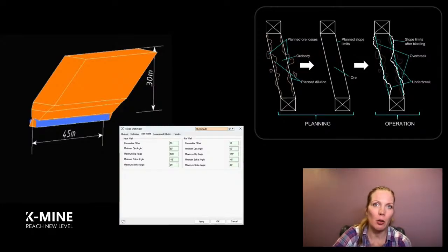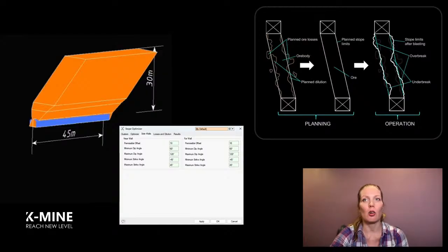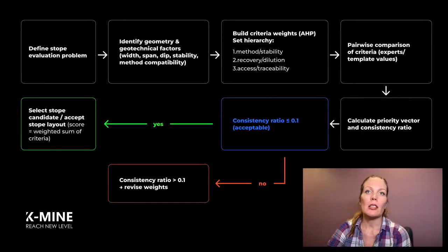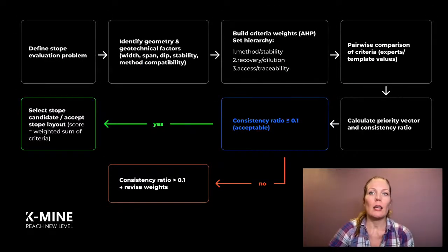In most academic work, including surveys on joint stope layout and scheduling optimization, this is exactly what's missing. Geotechnics is applied afterward, and half of the stopes in the optimal solution can no longer be constructed in the rock mass. Once geometry and stability are connected, we can add multi-criteria considerations.